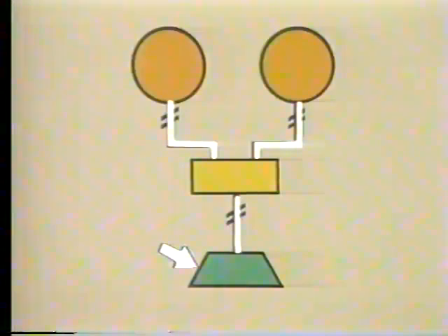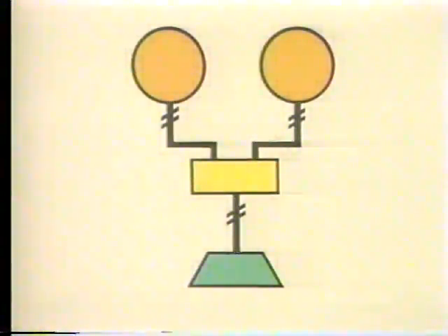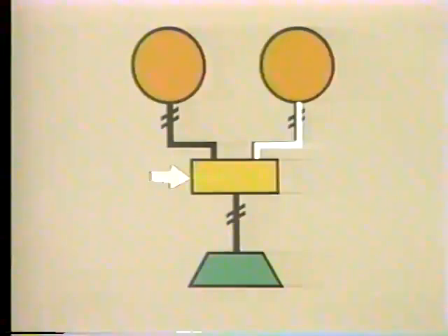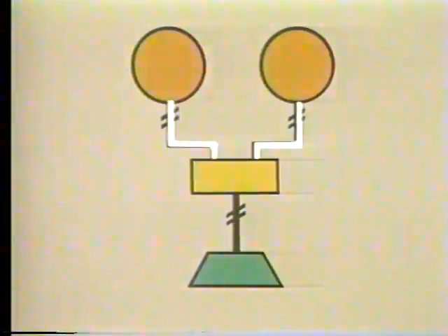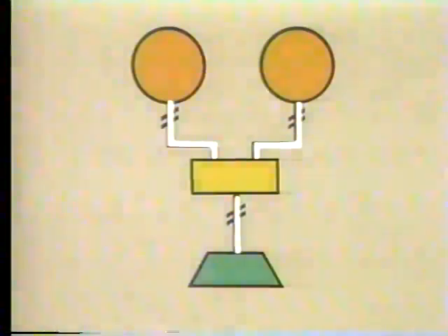Since there's only one final control element in this simple ratio system, the system can manipulate only one of the two monitored variables. More specifically, the final control element acts to increase or decrease the value of the manipulated variable. As the value of the manipulated variable changes, the measuring element senses the resulting change in the monitored variable and produces a change in its output signal. This signal is fed back into the controller. When the input signal equals set point, the output from the controller holds the final control element in the new position, and the system is balanced at the proper ratio.